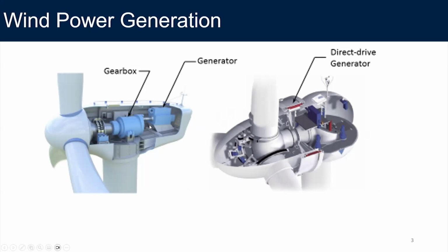although you tend to think that the gearbox plus the generator might weigh more than the direct drive machine, we find that the direct drive generator weighs more than the gearbox and generator combined weight. That's mainly because when you go into direct drive generators, they need to be low speed. And then as a result, the weight of the generator becomes really high.